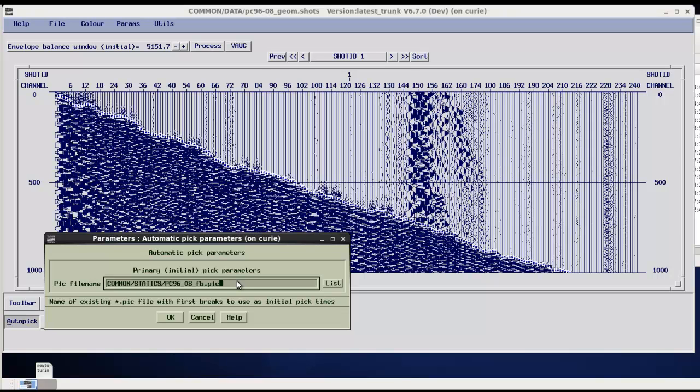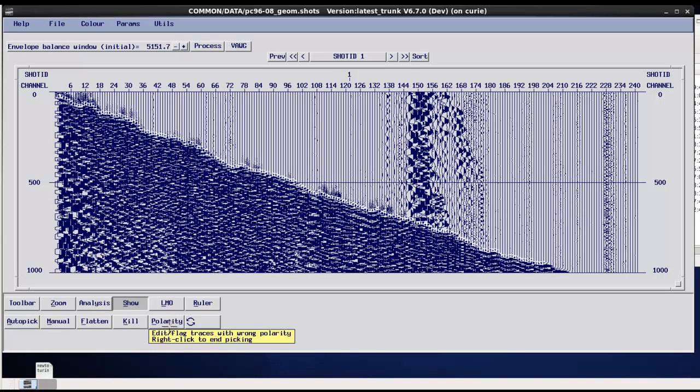You've come out, QC'd them in RefStat and been a little unhappy with what you've got. You can then take that set of picks in as a seed for your update, and basically have your approximate pick method be those initial picks, and then refine those picks based on the main pick methods, etc. So hopefully improve them and refine them down to a better set of picks to input to RefStat.